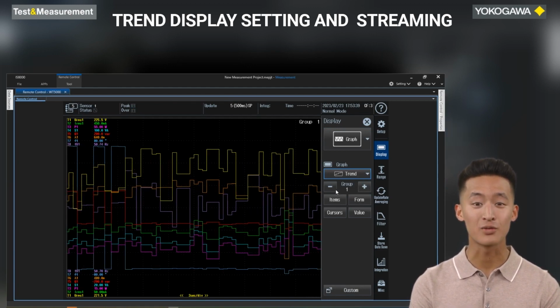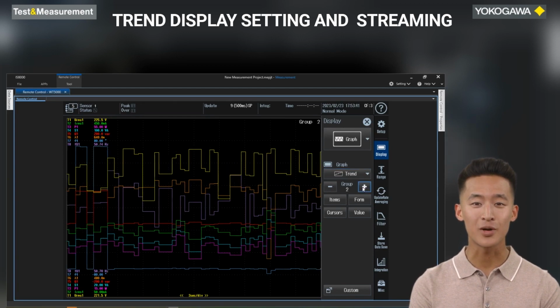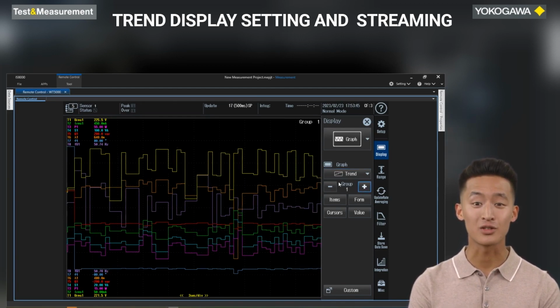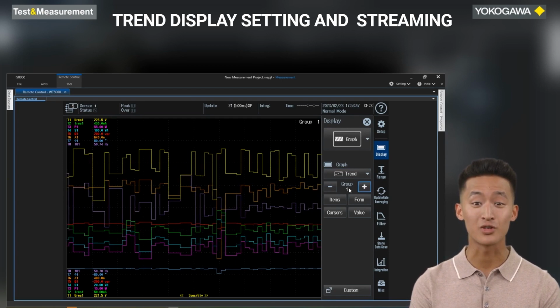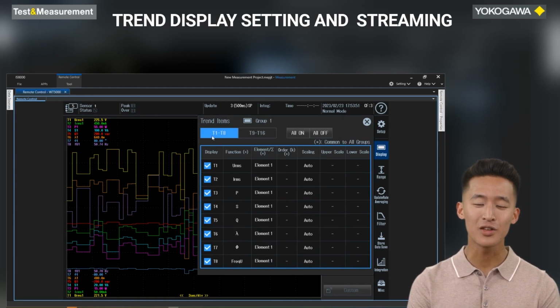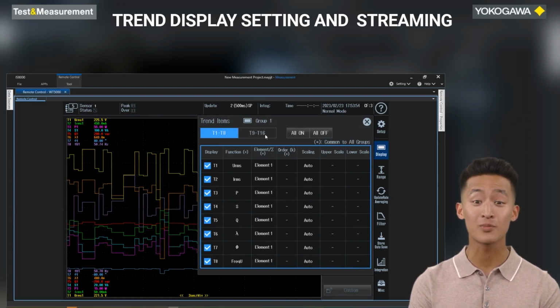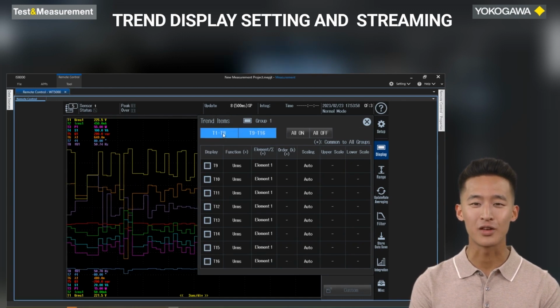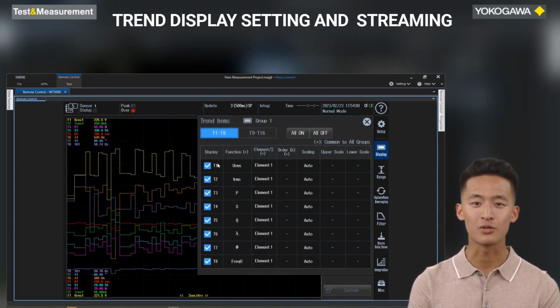In trend graphs, we can group measurement parameters and combine up to 16 parameters under one group. We can make 4 such groups to have maximum parameters under trend graph for analysis. Let's configure trend traces for each required parameters. For that, click on items, which will open up a window where we can select and configure required parameters to the available traces.